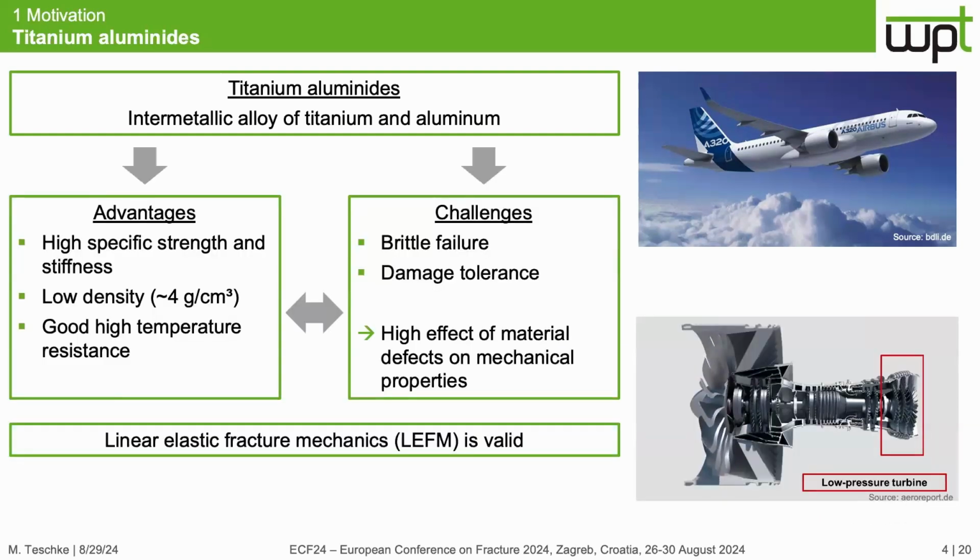They are very suitable for this application since they meet the high requirements regarding strength, stiffness, density, and high temperature resistance. But there are also some challenges like the brittle failure and damage tolerance, which makes this material very sensitive to local defects, which affect the mechanical properties. Due to the low ductility, linear elastic fracture mechanics is valid for most applications of this material.